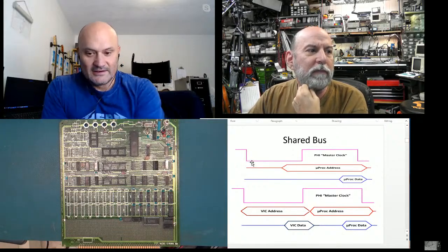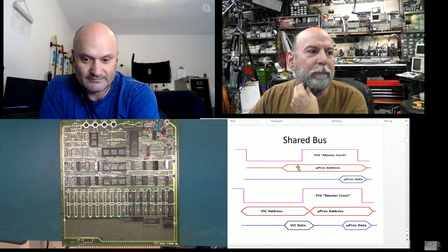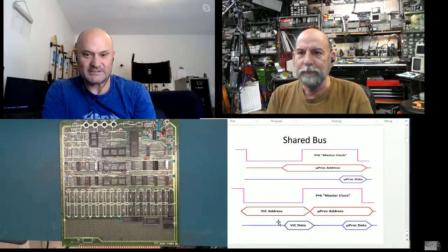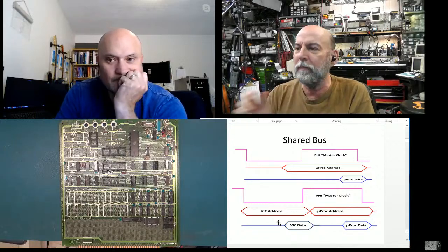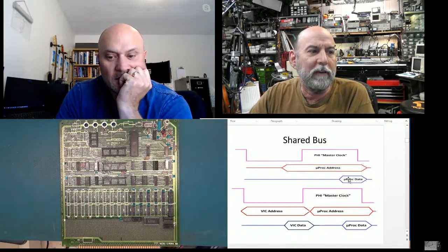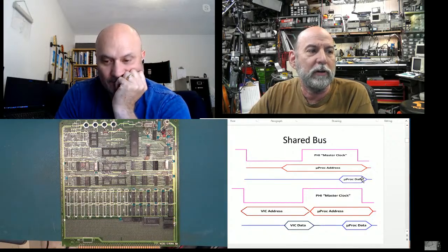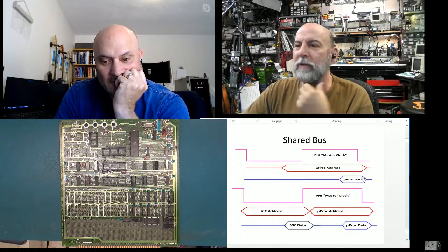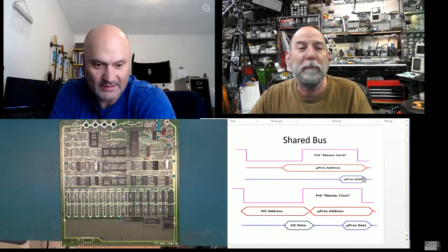Normally in a 6502 cycle, somewhere during phi low, the address becomes valid, and then at the end of the cycle, the data is valid right here. The falling edge is when you take the sample, right? Yes. Now you had to meet the setup, meaning it had to be there like 45, 50 nanoseconds ahead of time. And then it had hold time. There's like 10 nanoseconds you had to hold it after. That was the technology of the day. Stuff wasn't instantaneous. You had to propagate.